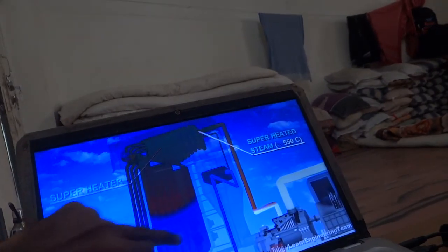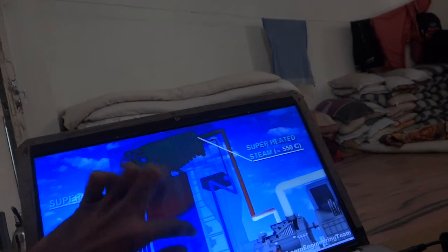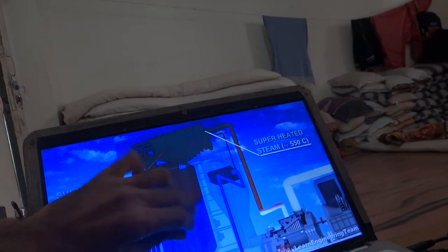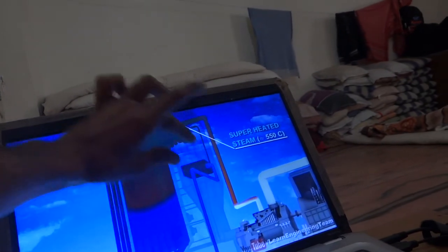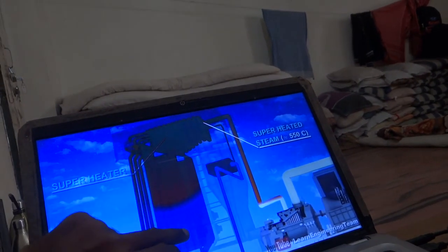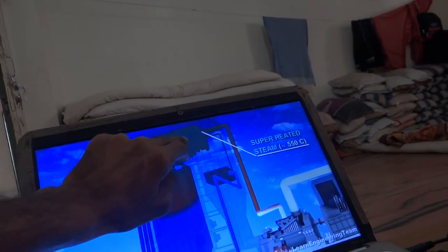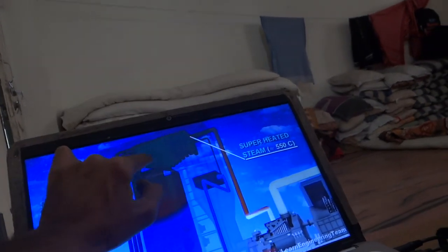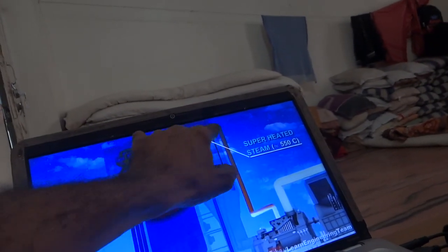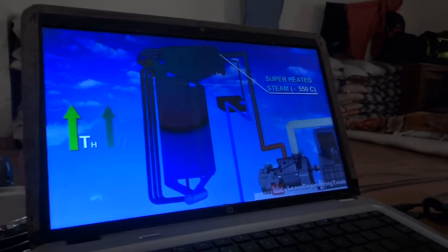They already have tubes here, and all of these tubes are going on, and here the coal is being sprayed, so the whole unit is full of flue gases. So now water is converted to steam, and that steam is also heated much more. How? The whole unit is full of flue gases, so they provided more tubes so that it will be heated more. The higher the temperature of the steam, the more efficient the cycle.